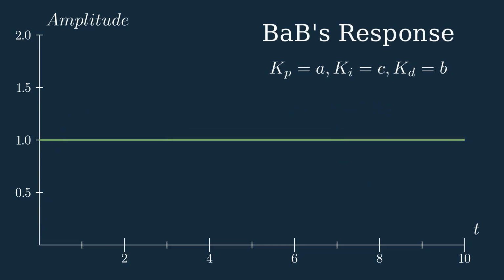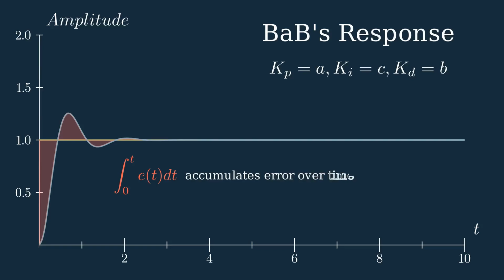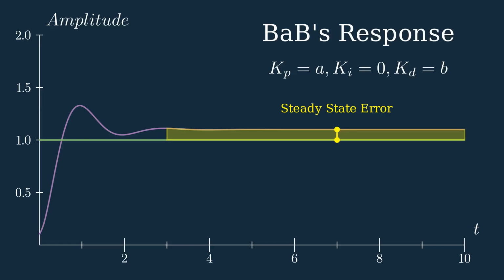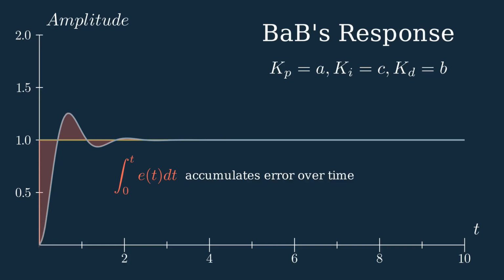What the integral component does is accumulate the error over time, keeping sort of a memory of the system's response. This will account for any weird deviations, such as that yellow region shown previously, and compensates accordingly depending on Ki. If you want a more theoretical explanation, I recommend looking into the final value theorem along with what happens to a transfer function when you add an additional pole to the system,